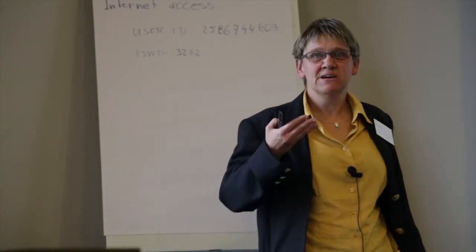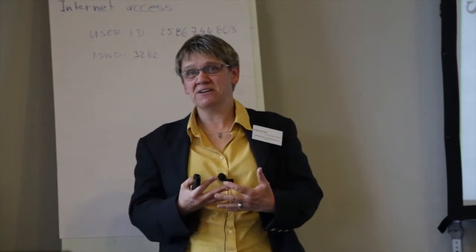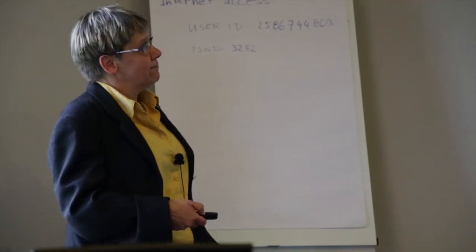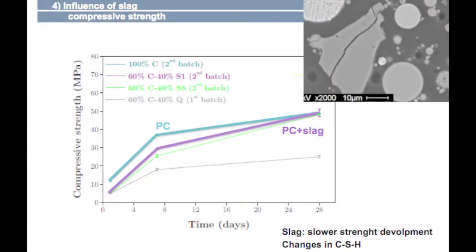So this instrument Peter has shown this morning offers us a completely new way to look into the structure of the CSH. I come to slag. Slag is a bit more reactive than fly ash. You get reasonable strength development. And again, you change the CSH.